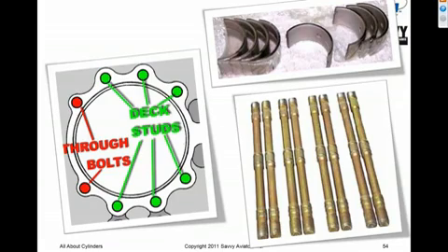Cylinder removal involves relieving the torque. Removing a cylinder requires relieving the torque on 2 of these through bolts. If you remove multiple cylinders, you wind up relieving torque on multiple of these through bolts. If you do that and then you turn the prop, which you basically have to do to position the piston for cylinder removal and reinstallation, there's nothing holding the crankcase halves firmly together, and you run the risk of displacing a bearing and causing lubrication failure and a catastrophic engine failure. So, the simple act of removing and reinstalling a cylinder has the potential to set up the scenario for a